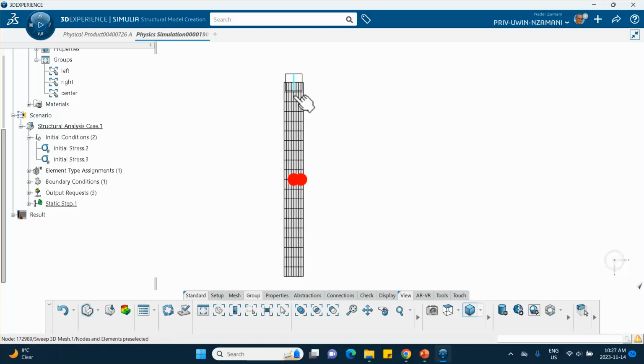In other words, it tries to put more compressive stress in the middle so that it can balance this. Remember, there was more tensile stress in the middle section. And what it does, it bends so that it introduces a compressive stress in the middle section so that it offsets that more tensile stress so that it becomes in equilibrium with that.